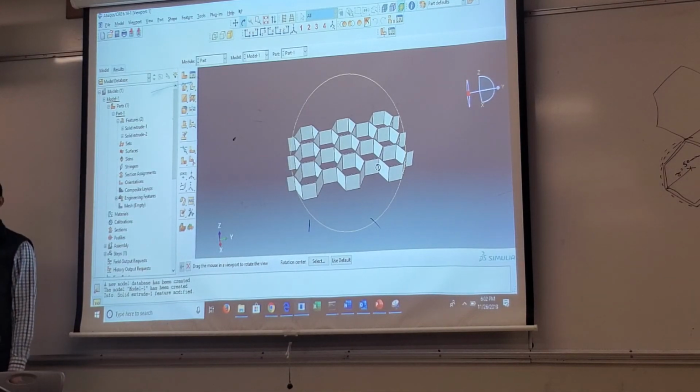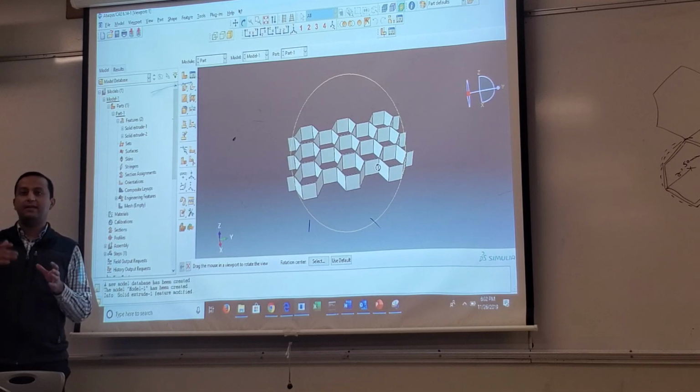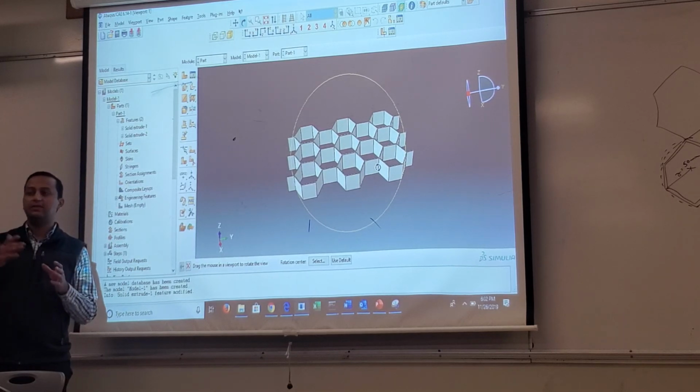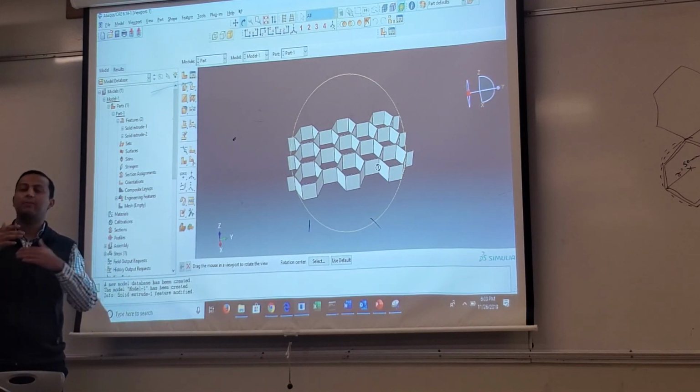Right? I have not asked you to follow with me, the only reason being that it will take time to understand what are the things that you need to keep in mind while extruding it. Does it make sense? So you follow right now, right? First you have to create one cell. Once you have created one cell, then you actually use pattern feature to create 3 by 3 data structure. Once you get a 3 by 3 data structure, then you basically use translate feature to combine together.